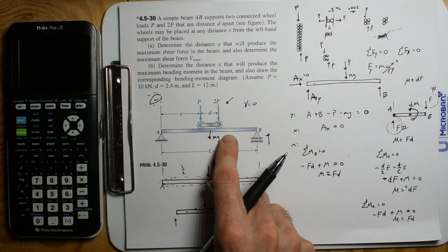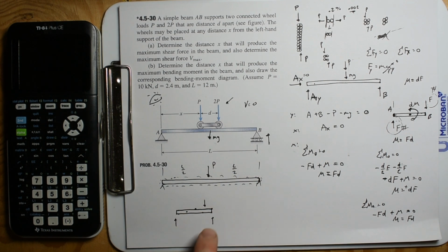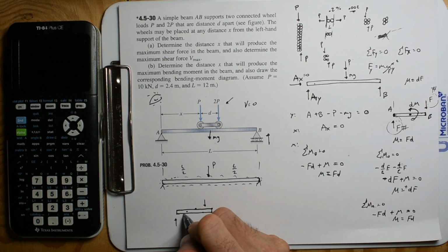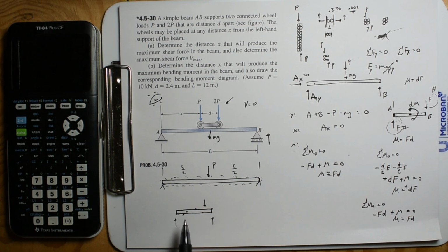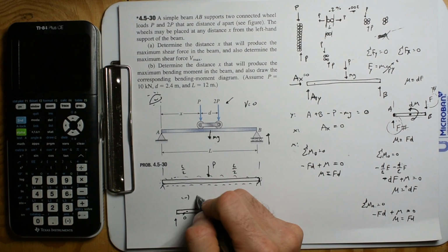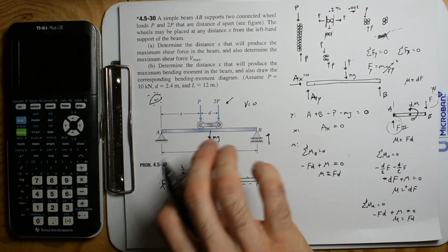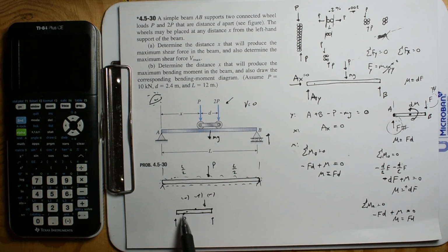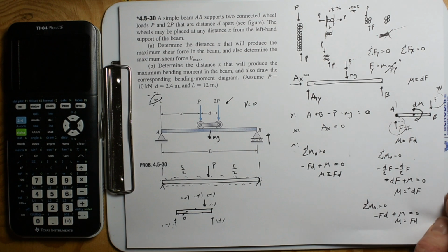But when we have statics problems, the forces are such that it's not causing any moment about any point on this. So we could literally tack it anywhere, and then we could use that point, let's say the point O, and then we could see that we have a force over here, that distance, that's going to cause a negative moment. This one's going to be positive, and then this one is going to be negative. And these two that are negative are going to balance this one that is positive. You know what I mean? So that's kind of what happens with the sum of the moments are equal to 0.